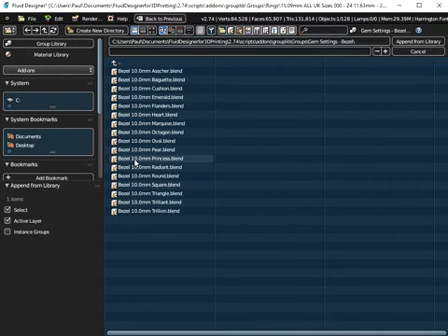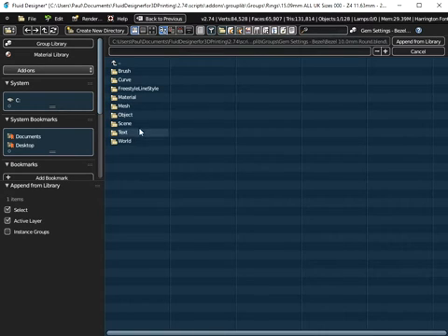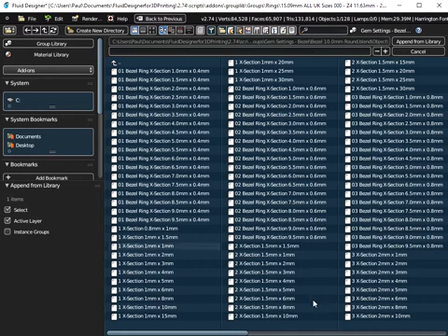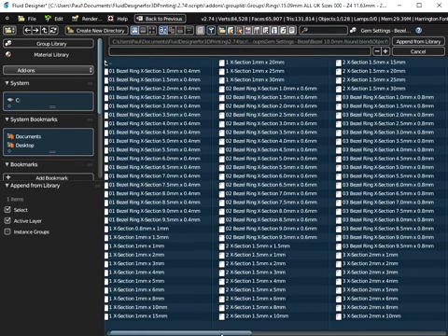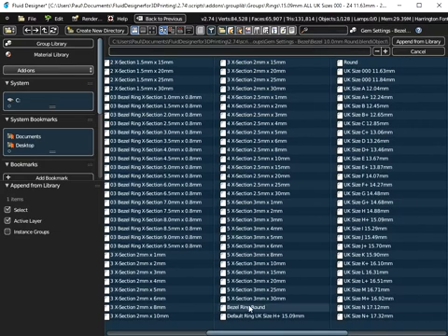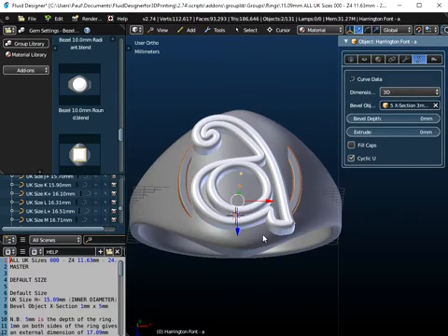It's a gem setting bezel, and we're going to use the round one, and the default size is 10mm, but we'll change that. So I need to append the object. And so the objects that I don't want all these cross sections. I just need the bezel ring round, which is the bezel itself, and the gem. I'm going to bring in the gem as well. So if we append those two objects from the library,